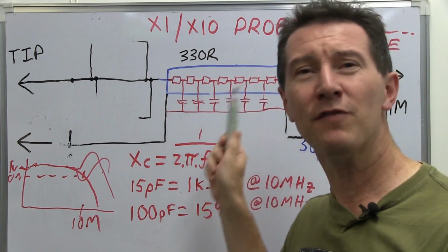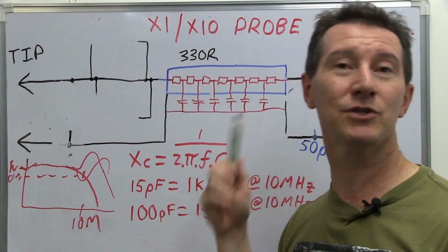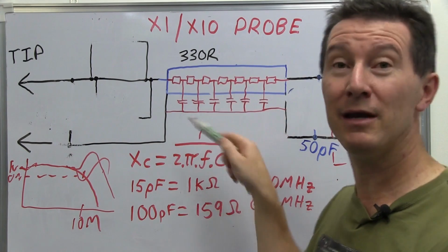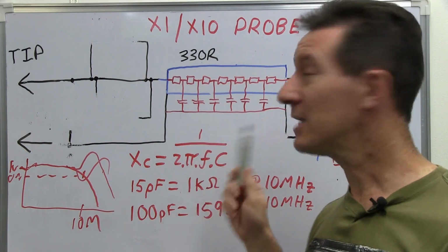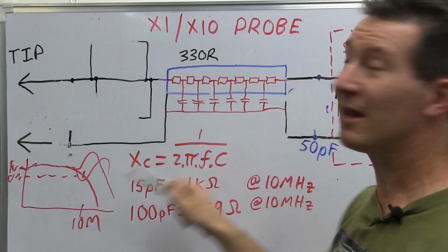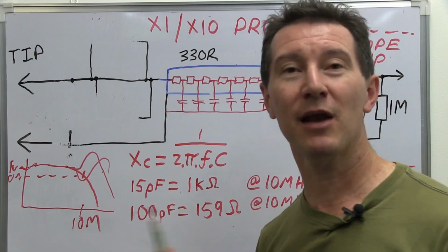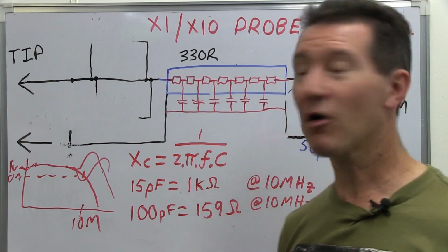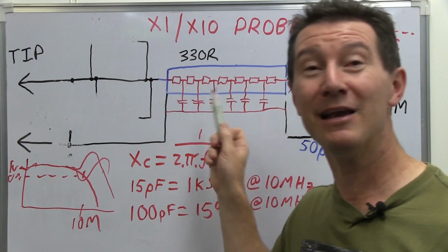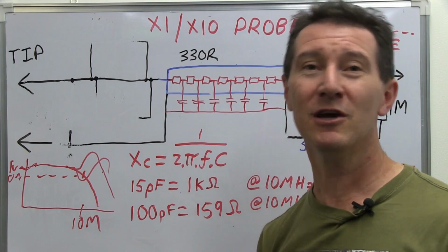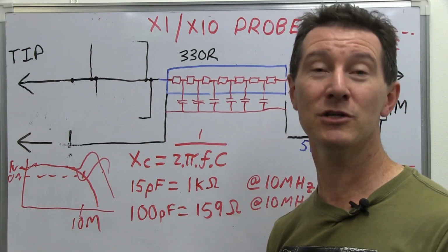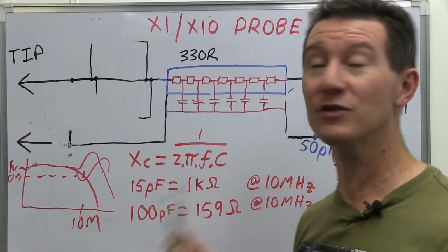It's a lot of art and science that goes into this, and it was originally developed by Tektronix way back. They were the ones who pioneered the lossy transmission line technique. And they're very cleverly and very carefully designed to get your 500, 600, 700 megahertz bandwidth passive probes, which you take for granted these days, but you're paying a lot for that. There's a huge difference between a cheap 60 megahertz probe and a 600 megahertz passive probe, and that's often why they cost so much.